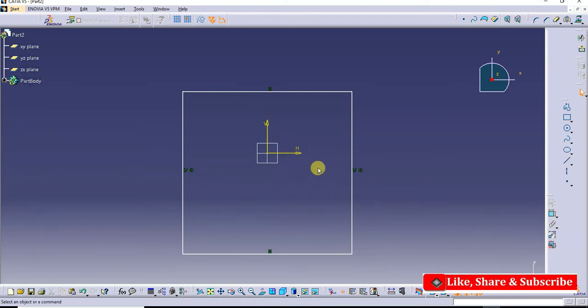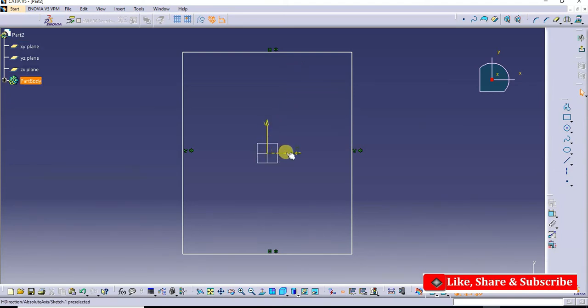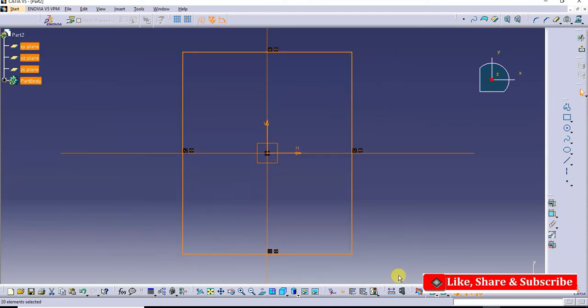I want similarly this dimension to be symmetric about this axis. So what you have to do, you need to select these two lines. Press the Control key on the keyboard, select this line, then click on this axis line and select the symmetry. So the sketch has now become symmetric about this axis as well as this axis.